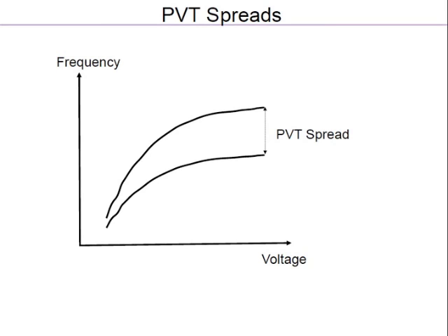Now we saw that for this frequency versus voltage curve, there is no single curve which defines it. For a particular design, there is a family of curves based on the process condition, because there is no fixed threshold voltage; there is a spread in threshold voltage. The operating supply voltage could be a little different. You are applying 1.2 volts to the chip. Another chip is also given 1.2, but it might be a little bit off, 1.25 or 1.15. There is always a tolerance given. Similarly, temperature of operation could be different. So you see there is a spread in the frequency versus voltage.